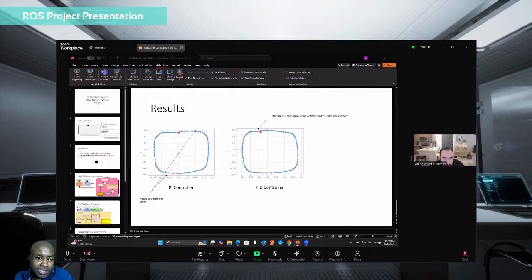And so what happens, you see this dip, this overshoot and correct. This is as a result of the angle that we exit out of the corner action. I've tried to make the corner action more aggressive. I've tried to make the linear component slower so that it does a toot toot toot and we come out. But ultimately, so long as we're not reading corner action, we're going to alternate between the predefined curve and the feedback control loop.